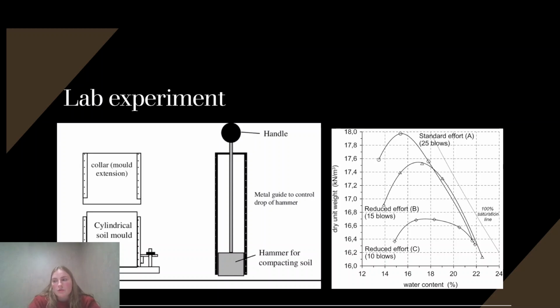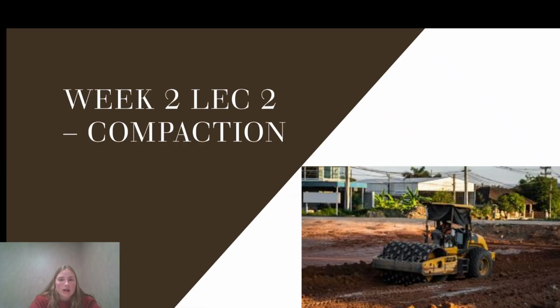And then the last thing to mention with compaction are the construction site machines and the number of passes. On a construction site, like in this photo, someone sits in a machine like that and goes up and down, and they pretty much do that for 8 hours a day. There are specified numbers in the course notes, but realistically, they're all approximations because it depends on the type of roller that you use or the vibrating machinery. So it's highly dependent on the site and the soil that you're working with. It will change drastically from site to site.